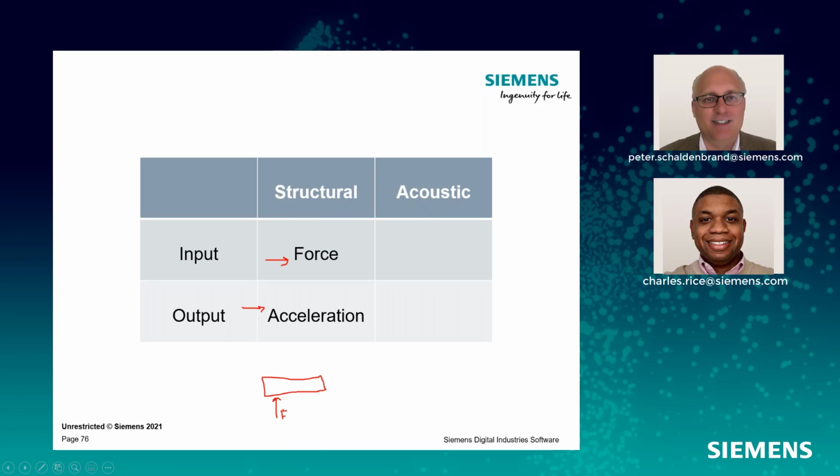If I apply a force here, there's a temptation to say, all right, I'll measure acceleration here, and say that acceleration represents the force, because I don't want to bother to put the load cell in. And then let's say I'd instrumented something over here, A2. Well, when I apply a force here, I'll also see vibration at A2, right? The acceleration is not always a good indicator of the forces coming in, because the system can respond. If I only applied the force here, I'll still see some response over here. So I don't really know the forces. So you have to be careful.